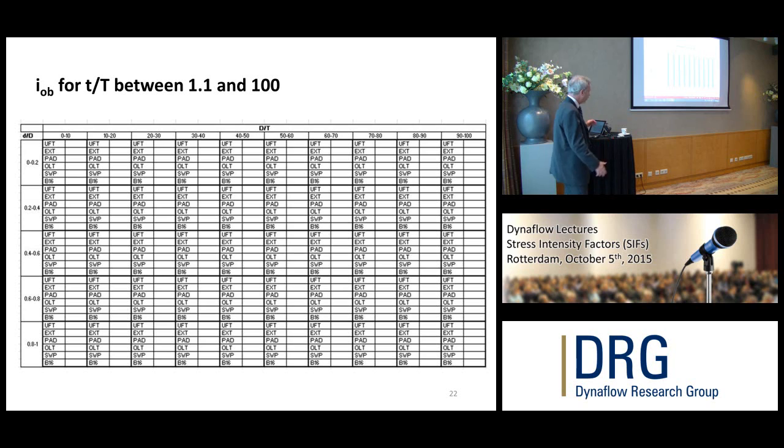And so there's a conservatism that is being added now for new SIFs. We're not just extrapolating up and assuming, well, we don't have any data, just extrapolate up. We're not doing that anymore. We run finite element calculations exhaustively, and a few tests now in this range. The ASME has approved about $150,000 for testing for the new year, so we'll be running some tests into this range starting next year.